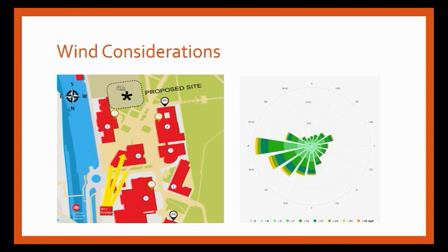I reviewed the average wind speed and direction of the wind in Salford to get an idea of which part of the building is typically vulnerable to imposed wind loads. This is usually the responsibility of the structural engineer, but this is sometimes overlooked, leading to potential weather damage. According to Meteoblue, the average wind direction in Salford is southwest and can get up to 38 miles per hour. This raises the need for extra care towards the selection of cladding.